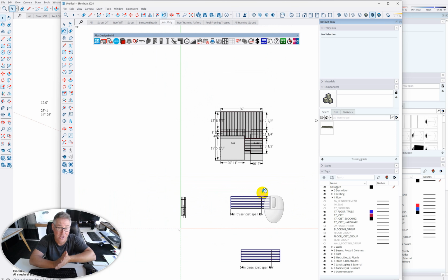So guys, don't forget, create all of your floor joists into spans according to the girder spacing, save those inside of your components, and then you can also back that folder up too, guys. Always a good idea, and you can share them with your friends as well.